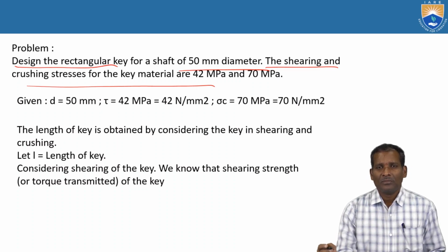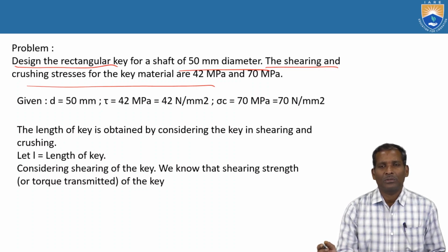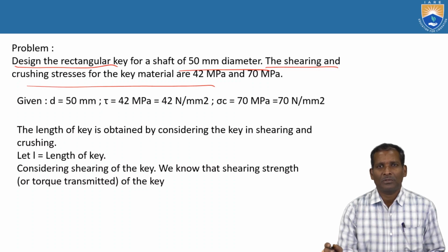Always the component should withstand the given permissible stresses. How to check? By comparing with the calculated shear stress or crushing stress, the value should always be less than the given permissible stress. Then only the design is safe. I will explain in the later slides.